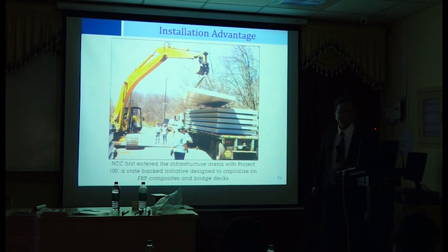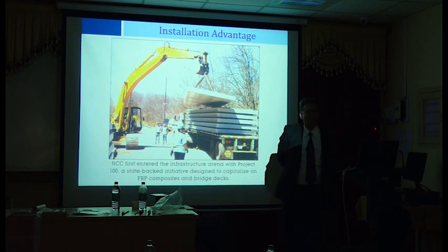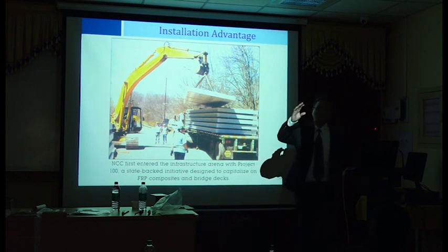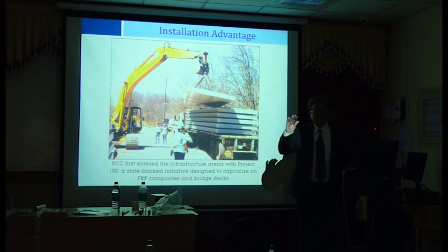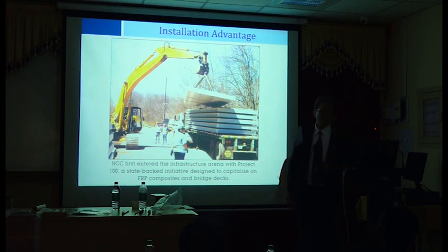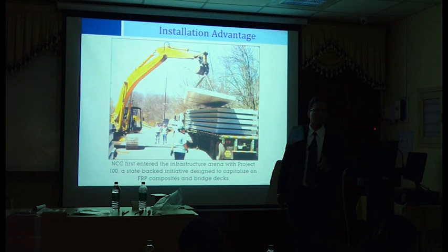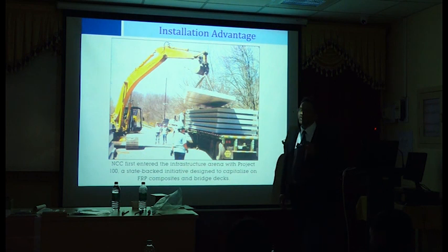Can you speak loud? By utilizing this FRP composites, self-weight reduction is the biggest advantage. Yes, absolutely. But in earth-retaining structures and dams, self-weight is the key. Right, I know. Then how do we utilize FRP composites in dams and retaining walls? Maybe that's not a suitable application. Or you place FRP liners on the waterfront. That's what I would do, because for gravity dams you definitely need concrete or something heavy. Yeah, I agree.